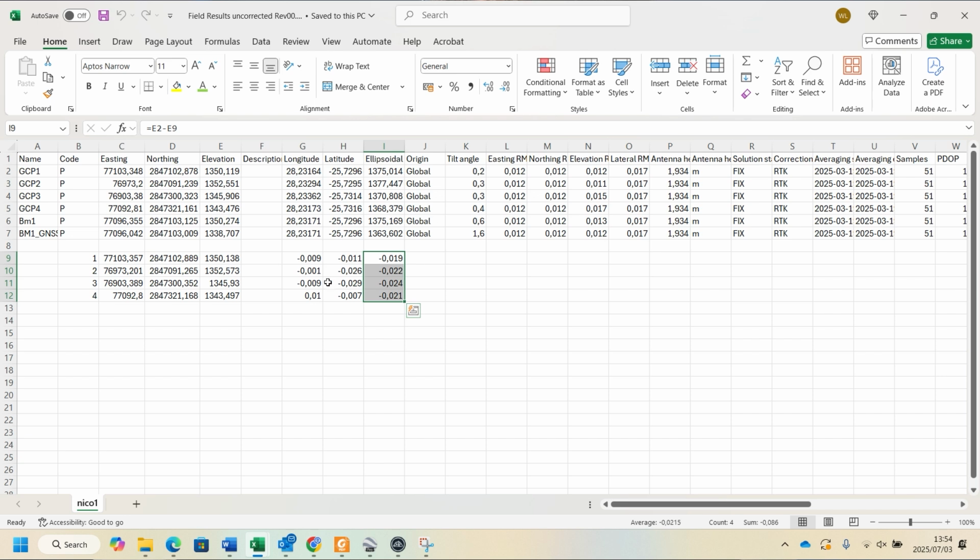and obviously the position could be off just on the way that I selected the points, but I'm very sure with a small marginal computation, or just even making sure on the actual points how I selected the points, that you'll be able to get this even to as close as 1 centimeter on the position, and I'm quite happy on a 2 centimeter elevation on the drone data for sure.